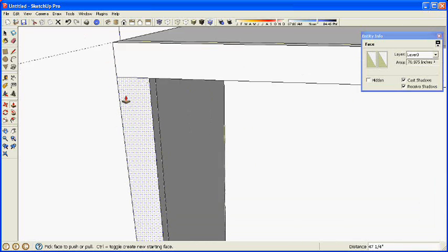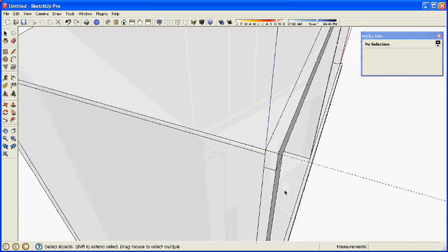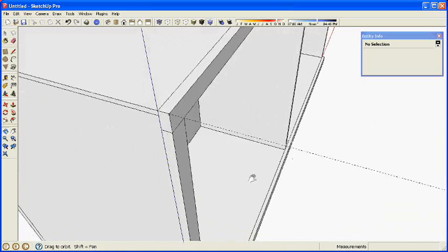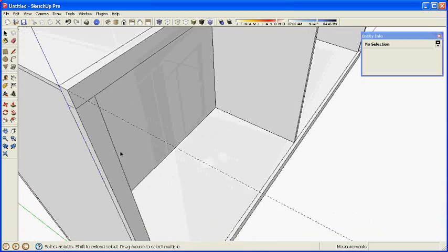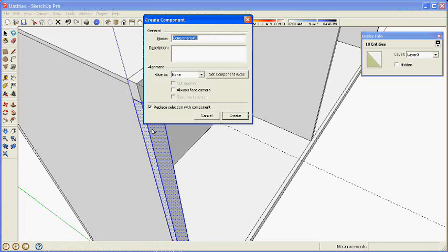Bring that up here. Assuming that the face frame style or rails are in the right places, the length of the style just has to fit in between. We don't really care at this stage what that dimension is, so let's not calculate and type that dimension. Let's just let SketchUp figure it out by bringing that up.